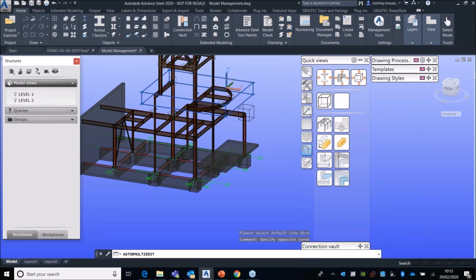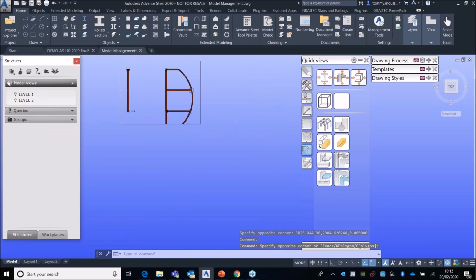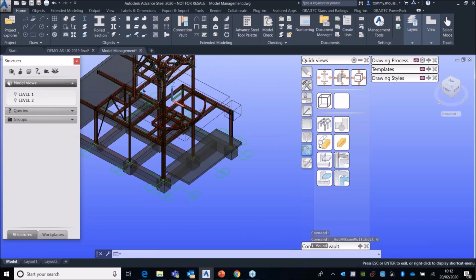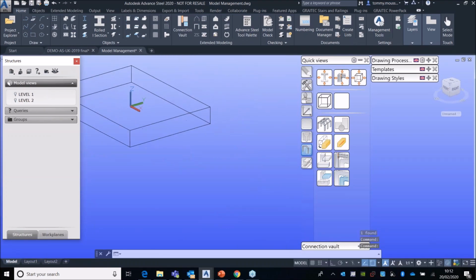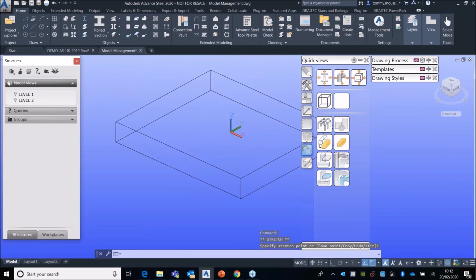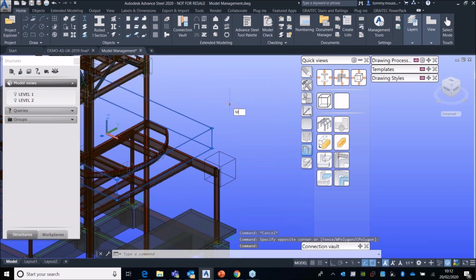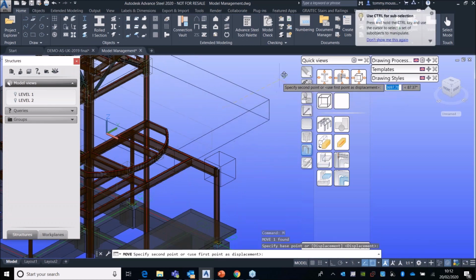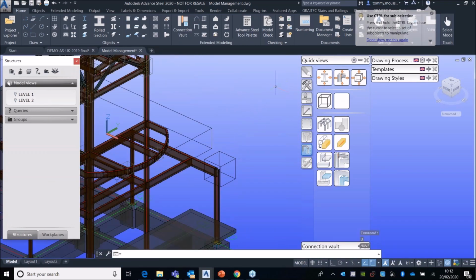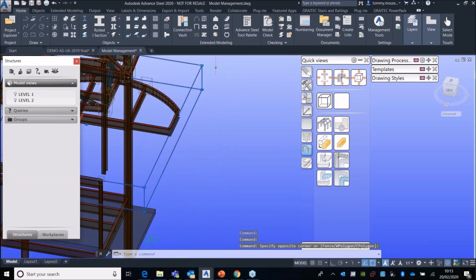And now if I were to double click on this item, of course, we can see here that we're missing a portion of the balcony. So what we could do is just double click to show the rest of the model. Notice here I did have grips, and we could just take the grips and adjust accordingly. You can also move your model view. So just to give an example, if I were to use the move command, you can simply displace it like so, on the left or right hand side. You can always change it in elevation as well that way. So if you ever make a mistake, you can always just adjust it afterwards.